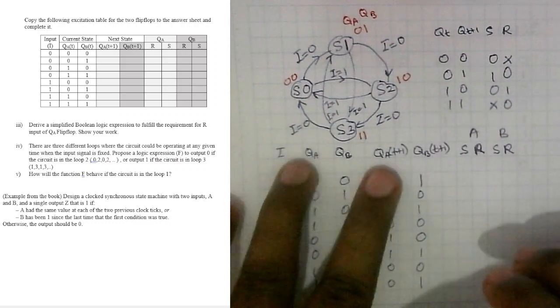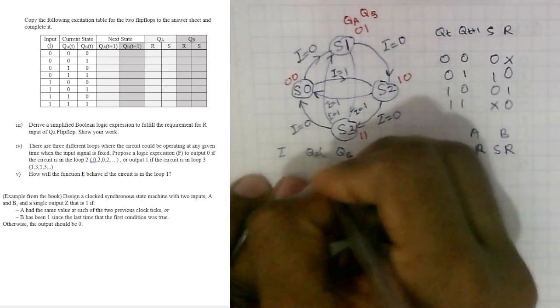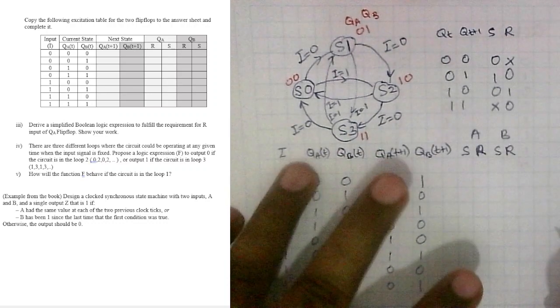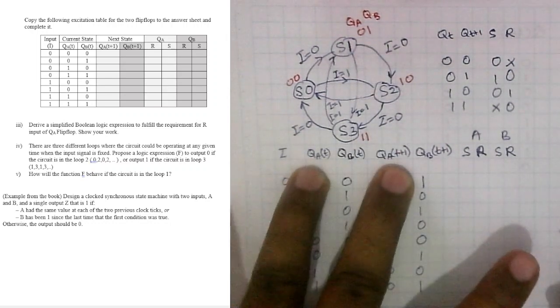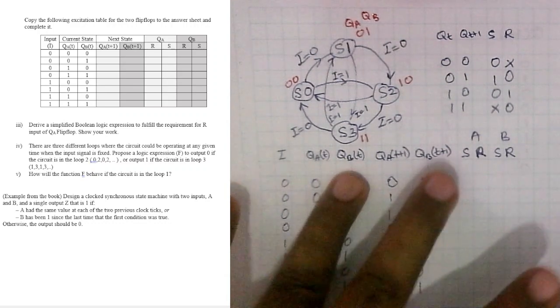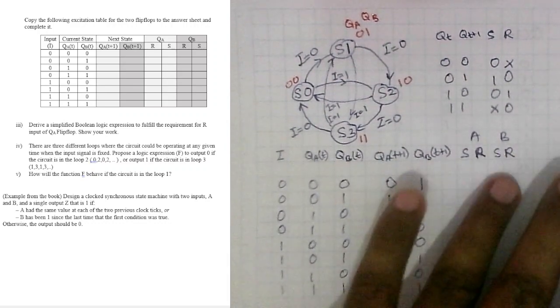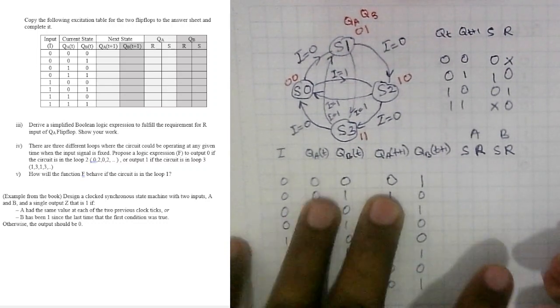Okay. So now let's see. Now there are two flip-flops, right? This is A at time t, and B at time t. QA is going from t to t plus 1, and B is going from t to t plus 1. So what are the S and R signals necessary for those transitions to happen? That's what we are going to determine here.